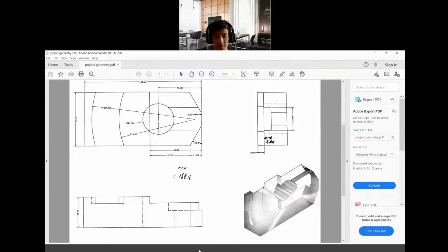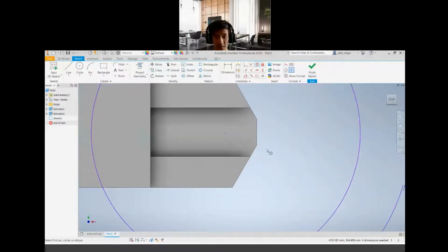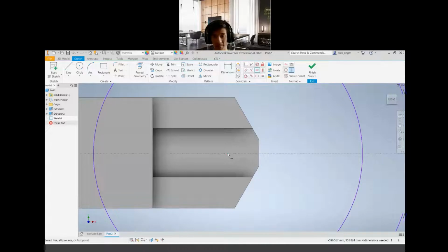Now, class, first I would like to go to horizontal constraint again. Select the center point here and pick the midpoint. Do you see the midpoint? Click. So now we put them at the same horizontal axis.